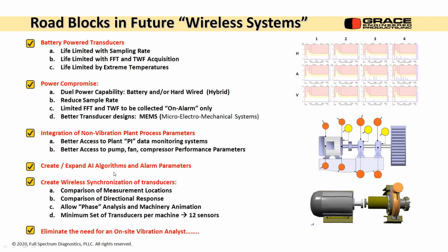Integrating plant process parameters, creating algorithms, and we haven't even started creating algorithms yet for real subtleties of overall vibration. Synchronization of transducers to get phase analysis. Basically the elimination of on-site vibration analysis, which I don't really approve of. I think it has a very useful function, but you know, if you supplement it with an off-site guy or a contractor, you can also do that.